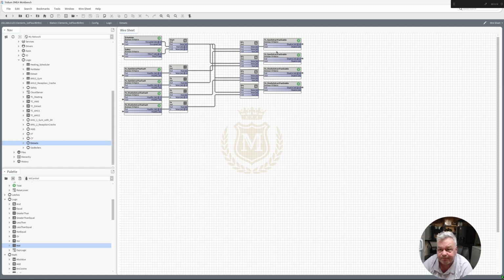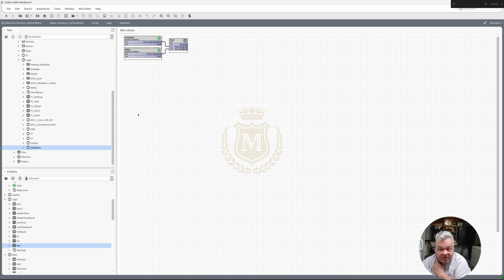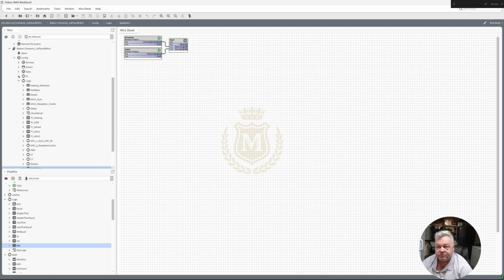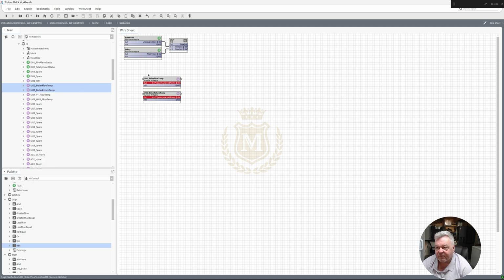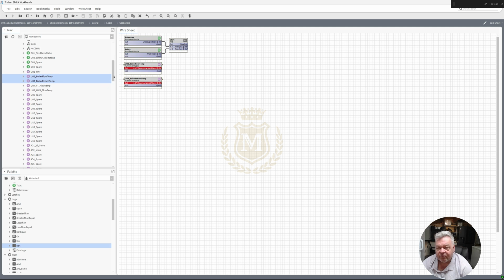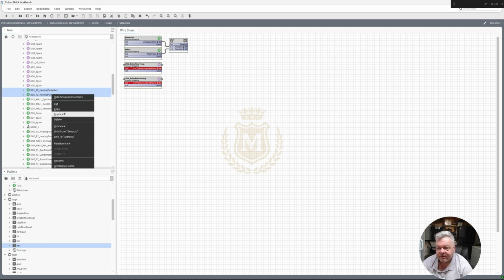Now gas boilers, which I haven't started the logic for yet. So let's start the logic for the gas boilers. The IO. So we've got boiler flow, boiler return. Paste that in there. I'll take out the alarm and the history in a moment. P1, P2, so these are my boiler heating pumps. Duplicate. I've duplicated it. They'll be somewhere down the bottom then now.